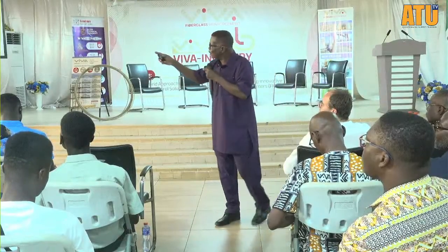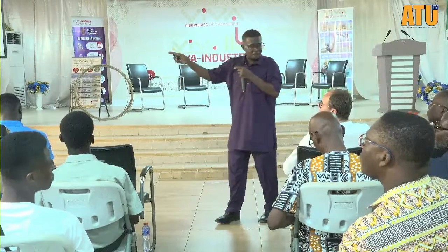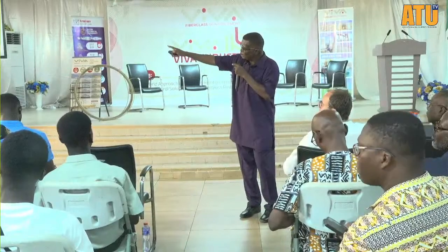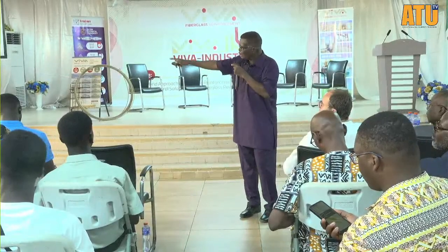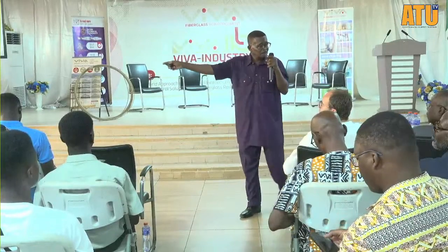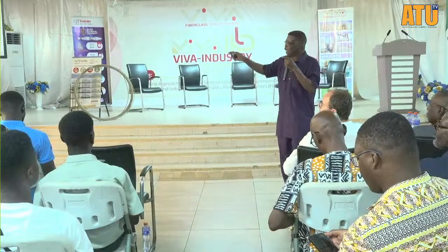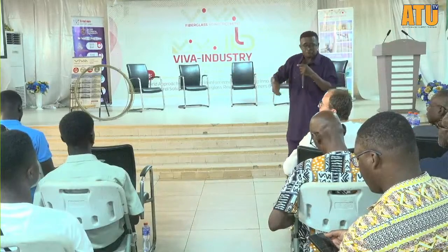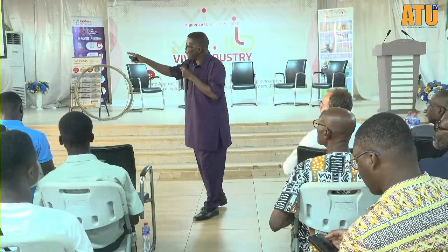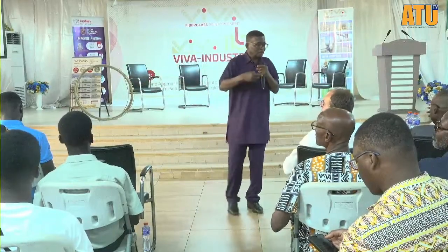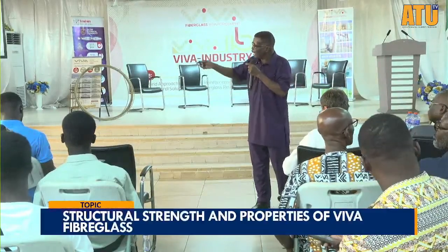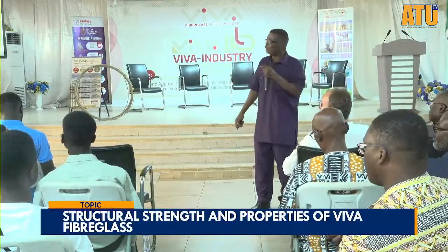This one is also interesting. This beam has steel main bars, and then the glass fiber has stirrups. So the failure is quite normal, no shear and so on. So glass fiber stirrups are effective. This one is steel, but because the spacing of the previous one is 165, so it's good. But here it is 300, so we are still getting the diagonal here.